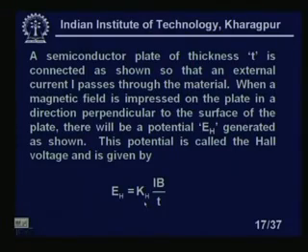We can see that if I can measure E H, I can measure the current also. If I know the K H of the material and I know the B, then this E H can be calibrated in terms of I, if the I is unknown. So by measuring E H I can tell the I, because this is the only variable. That is the reason Hall effect sensors are extensively used for measurement of very large currents, around 500 amperes and so on.